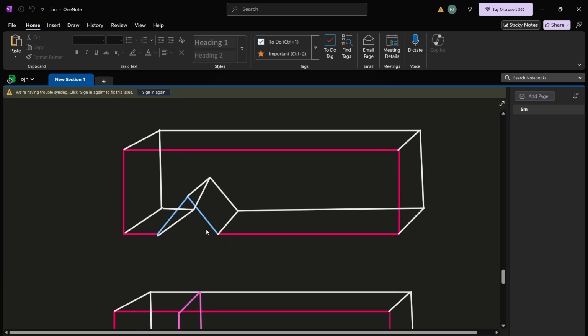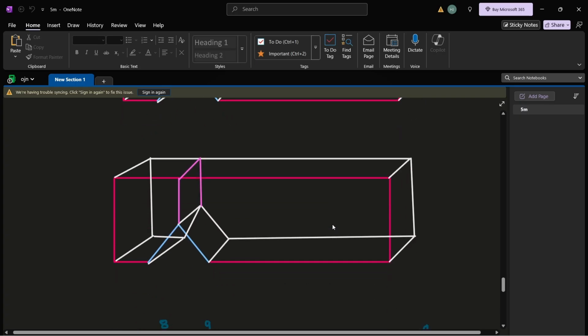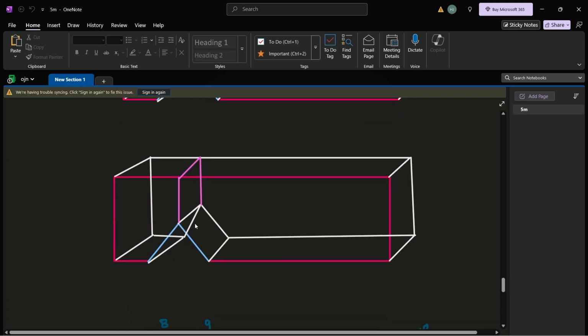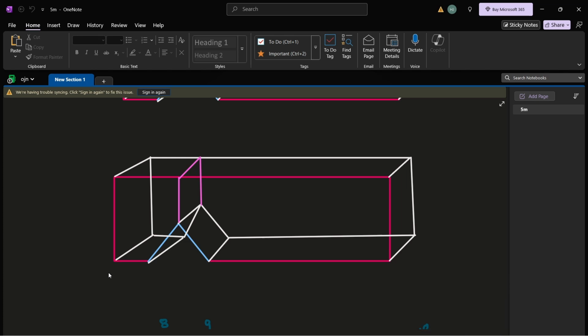If you see the block mesh, this is what a 3D block mesh will look like. A block mesh cannot handle a complete 2D, so we will just put the z direction, which is this, in just one cell, which will make it a 2D case. For a finite volume method, it's just one cell thick, so it's basically 2D. And blockMesh needs splitting, as we need only 6 faces per block, and we can have multiple blocks. So the first splitting will look something like this, and still it won't be 6-faced blocks. That I have explained in the meshing video as well.